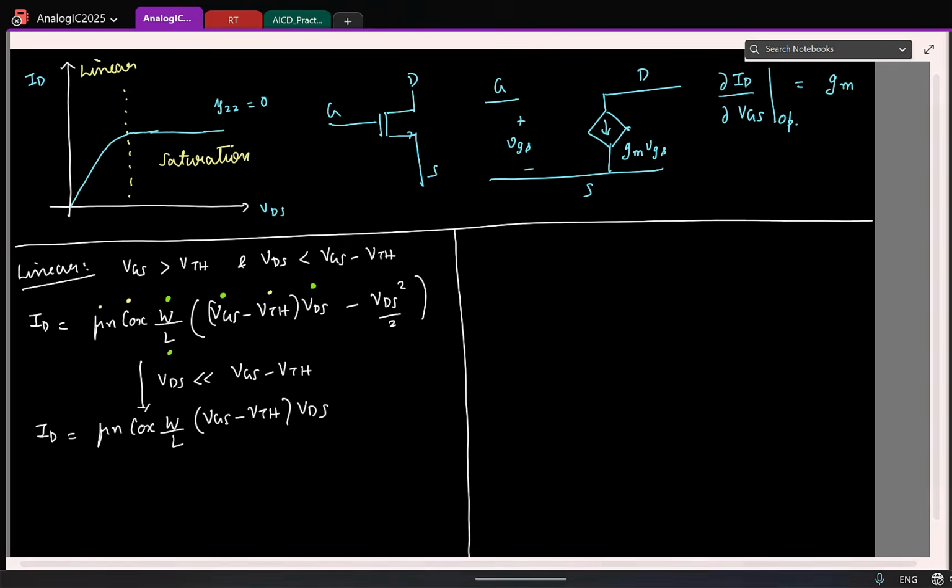So now you tell me if here the drain voltage, the drain current and the drain to source voltage are related in a linear fashion or a non-linear fashion. Does it make sense from the characteristic? Yeah, of course. For small VDS, sort of linear. Great. But of course, this is not where you want to bias your transistor.